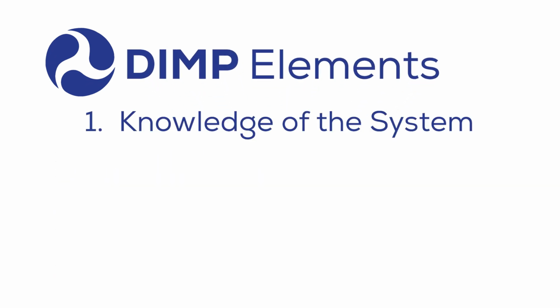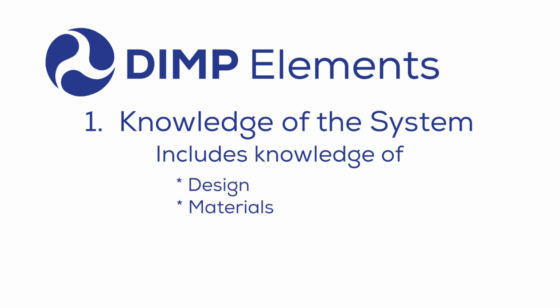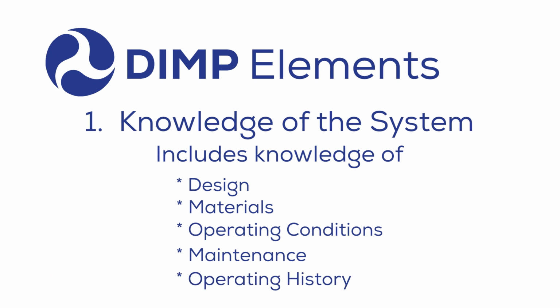First, knowledge of the system. Knowledge of the system provides the foundation for which DIMP procedures can mitigate risk. Operators should understand their system's design, material characteristics, operating conditions, maintenance, and operating history. They should work to close gaps by establishing procedures to gather this information.